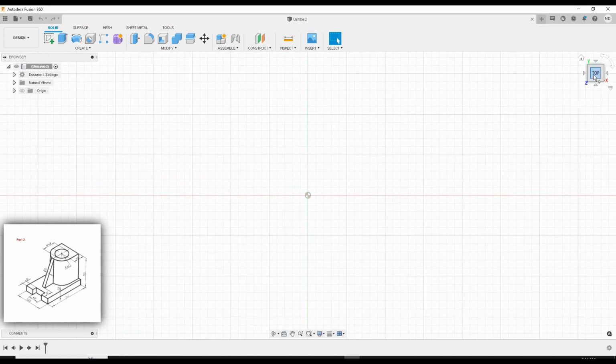Okay, we're going to go in the top view, and this is our box for our plane views, orthographic. So we'll make sure that we're in metric. All of the CAD drawings are in metric. Go to document settings. Yep, it's in millimeters.